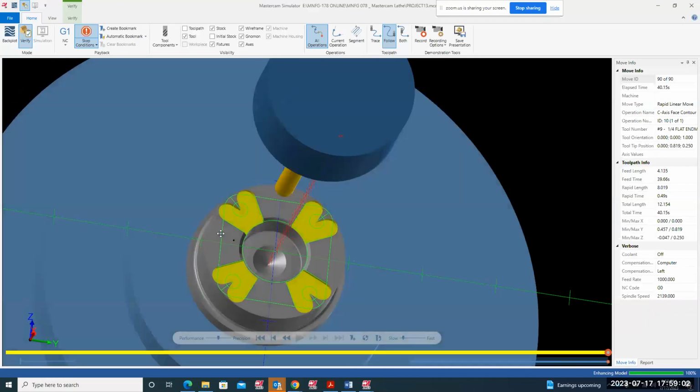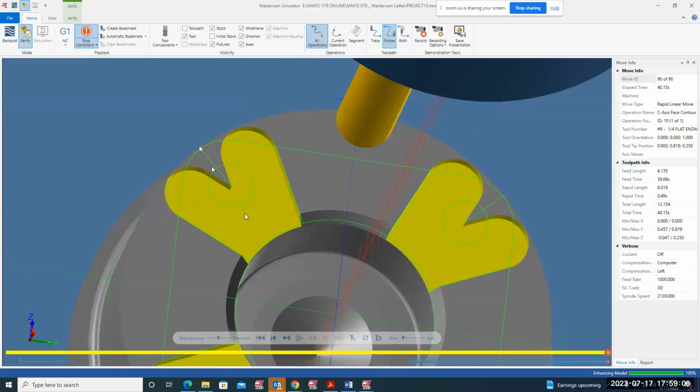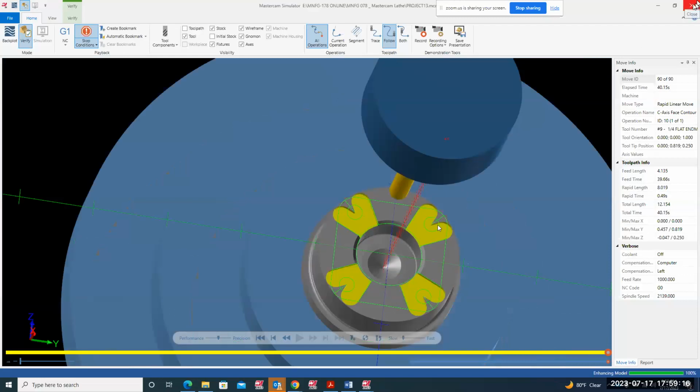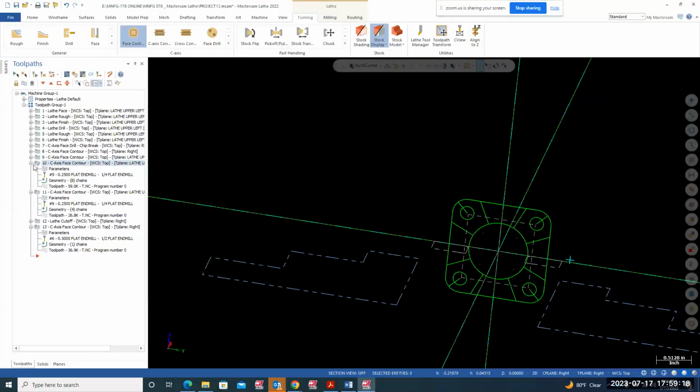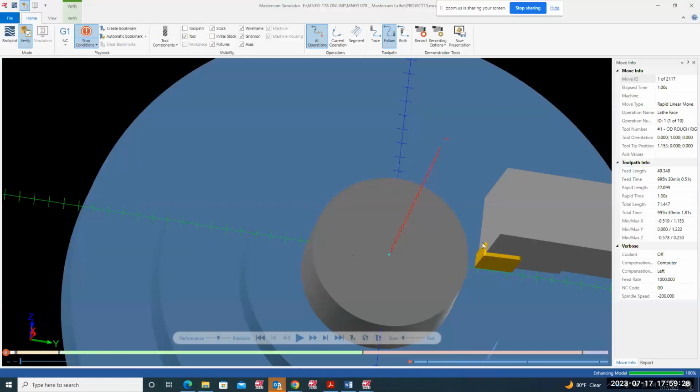That's how it's going to cut. And we have drawn this line, if you remember. Now we're going to program this line so it will take care of the extra material left over here. So if I'm going to run that part up to operation number 10, so start with 1 and go shift with 10, and we can see how this works.